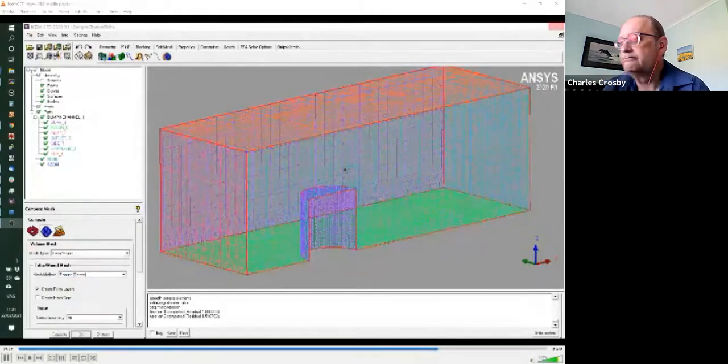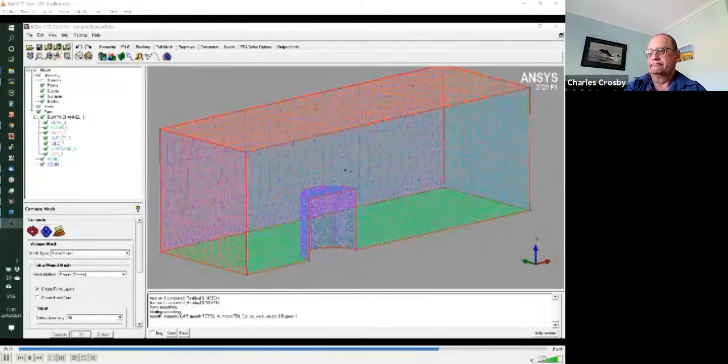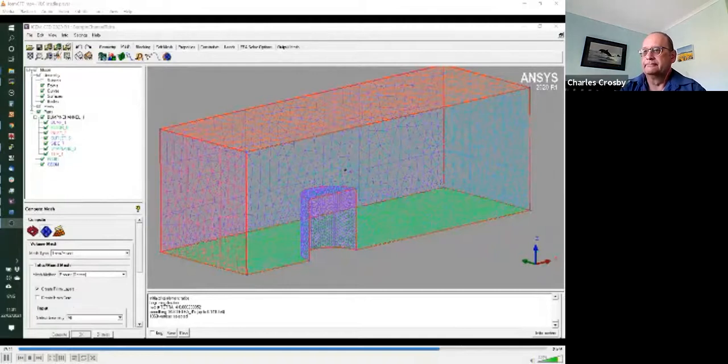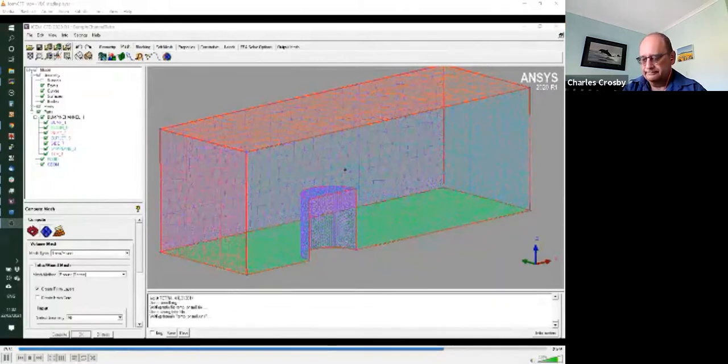It first creates a volume mesh, which it smooths before it starts working on generating the prism layers. Various tetra meshers do this differently. Others mesh the surfaces first and create smooth surfaces first, then extrude the prism layers from those surfaces, and then fill in the rest of the volume.